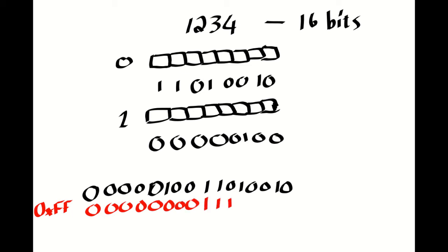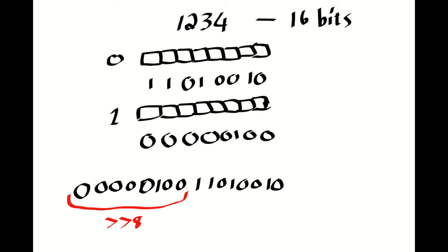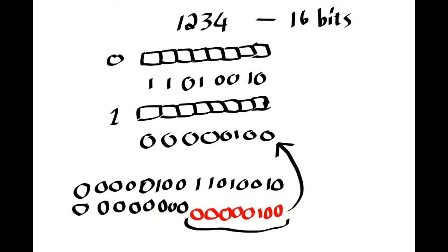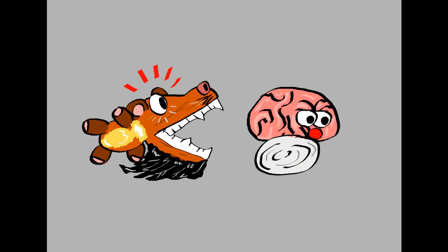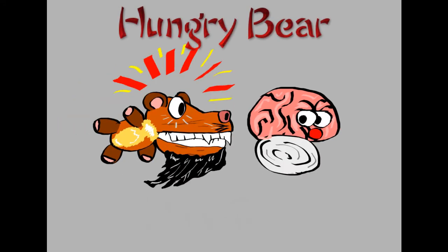If you then mask it with a mask that just has ones for the lower 8 bits, this is the result you get. It effectively zeroes out the higher byte, and then we store that in address 0. Then in address 1 we want to store the higher byte, so we take that and do an 8-bit shift, which gives you this result that I'm showing you now. It's all zeros that replace the stuff that shifted across, and that's it really. That's how you split it into two and store it. So that's a simple example, and I've already shown you the code implementation.